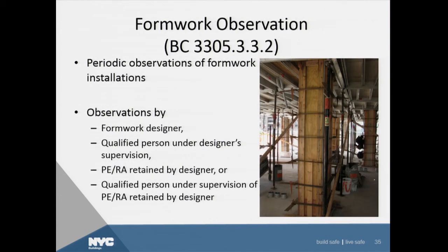And as a follow-up to that, there's also going to be a required formwork observation, periodic visits to the site by the formwork designer or someone under their supervision, either another professional or someone working under that professional supervision, retained by the formwork designer to make sure that the formwork design is being implemented.